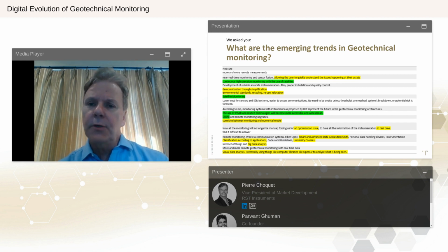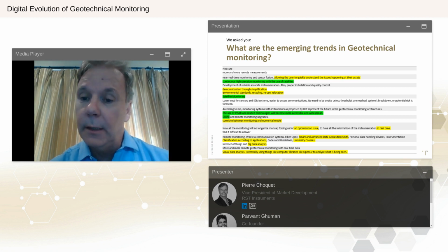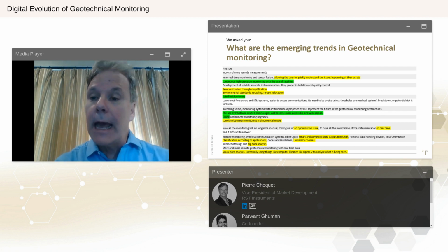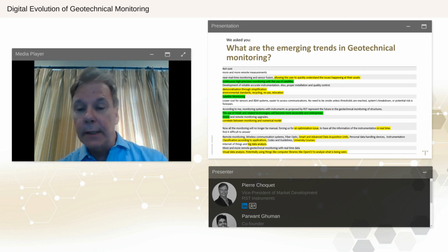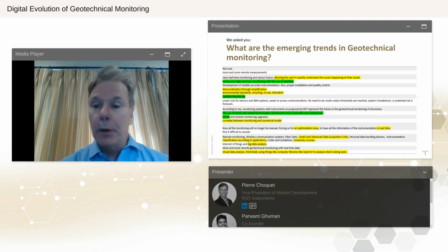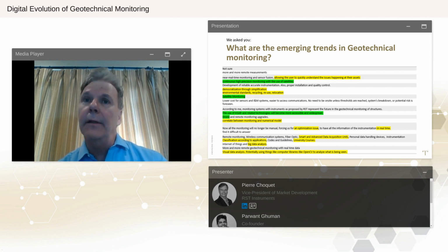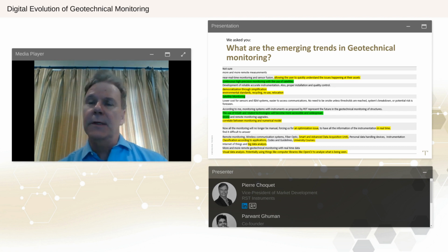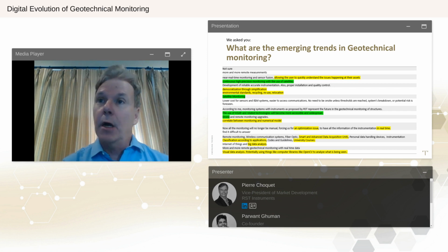But I think we should also not keep the status quo on the sensors front. I see improvements on sensors as well. Some have already happened in recent years, and some that we still need. For example, we're now better at monitoring very small ambient vibrations on earth, steel, and concrete structures, monitoring distributed horizontal and vertical deformation in the ground, distributed temperature profiles for seepage detection, multi-point pore pressure in soils and rock.